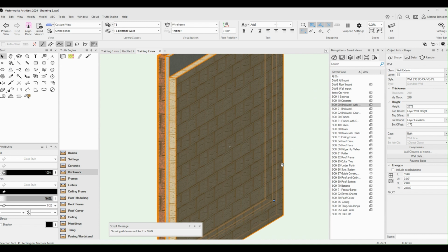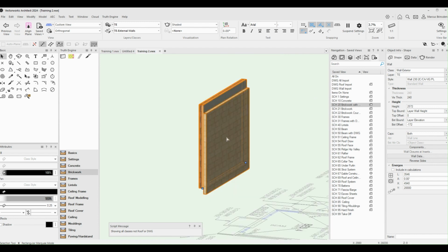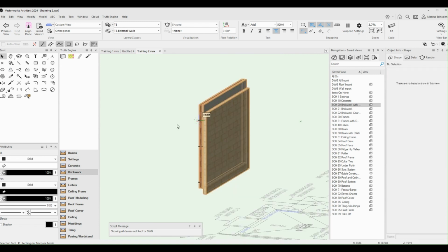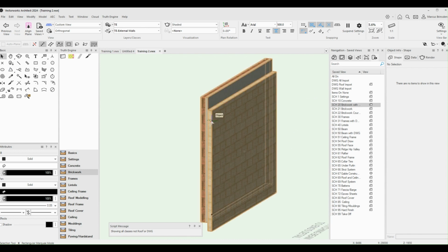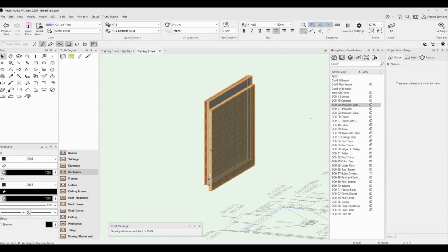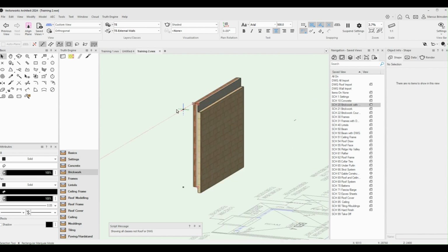You can see that's how this wall has actually been defined. By definition, this cavity wall, the two-course face is automatically dropped down 3 courses to allow for our eaves, and it drops down 2 courses to the footing. And this internal leaf always refers to the ceiling height. And again, the cavity goes with it. So quite a simple concept.